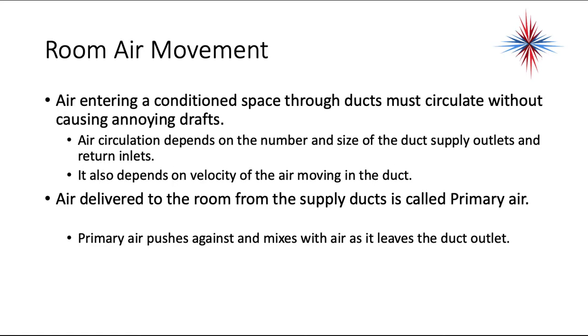Air entering a conditioned space through ducts must circulate without causing annoying draft. Air circulation depends on the number and the size of the duct supply outlets and return inlets. It also depends on the velocity of the air moving in the duct.